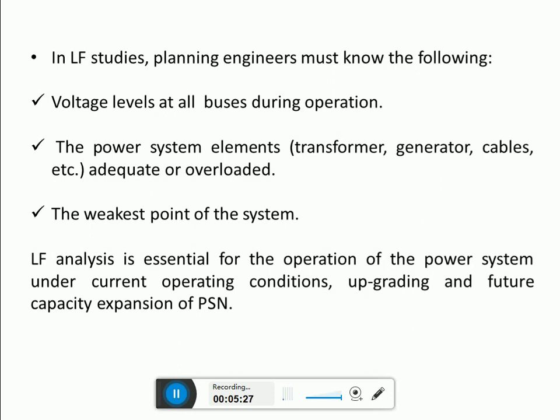So these are the importance of load flow analysis in power system. Now, in load flow studies, the power system planning engineers must know information such as the voltage levels at all the buses during operation, and the conditions of the power system elements, whether they are overloaded or in a stable position, and the weakest point of the system, like if there is any voltage violation or line flow limit violation.